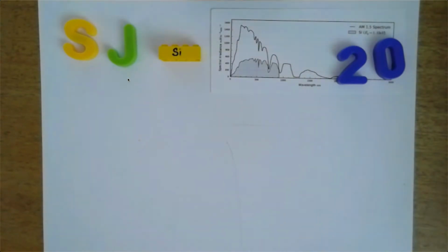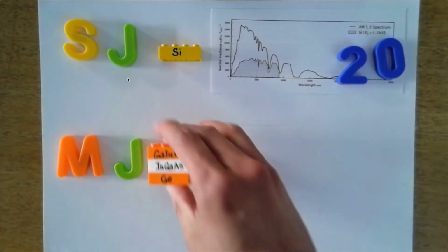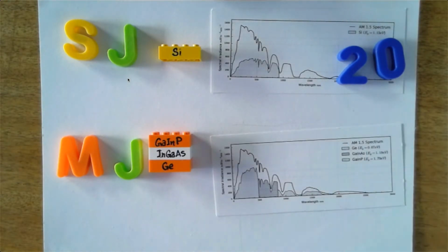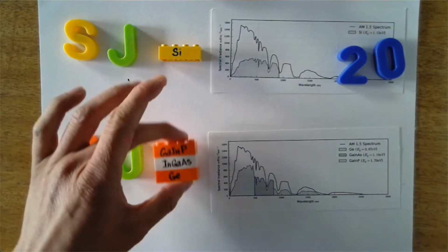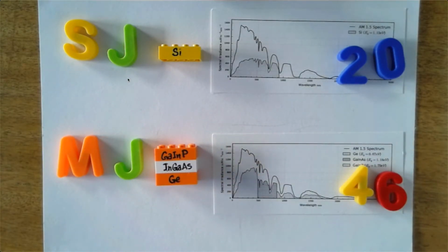And the state of the art in terms of solar technology these days are what we call multi-junction solar cells. And this is a typical one. It's a commercially available triple junction solar cell. And each of these layers in the semiconductor is designed to absorb a very specific slice of the solar spectrum. And as a result, more of the solar spectrum can be utilized. And the world record in terms of solar panel efficiency is held by one of these, at 46%, so quite a substantial improvement over the single junction case.